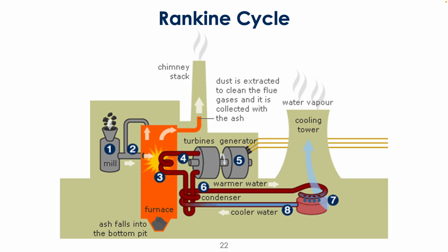So why don't we just send that water through the turbine? Yeah, exactly. The maintenance issues that would arise from impure water and sending that through the turbine would be a lot less efficient for the power plant, because you'd have to shut down all the time and be cleaning your turbine. So you have a separate loop that's cooling a pure stream of water that actually gets passed through the turbine.